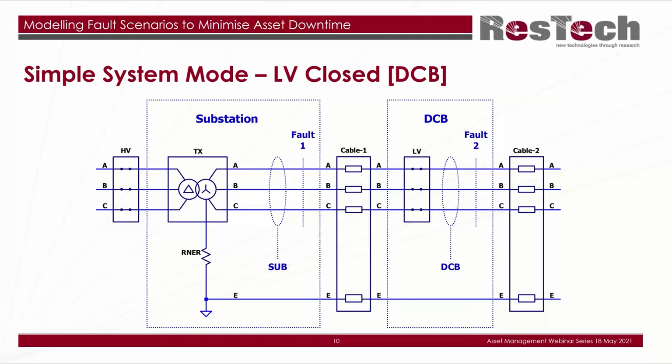Now, of course, if a fault occurs anywhere in a part of the system where power is applied, the fault is revealed. And we'll see the sequence of devices tripping will give us clues as to where the fault might be, and what the currents and voltages are doing will also give us clues as to where the fault might be. Okay. So this simple system has basically 4 modes of operation, and of course, if you have more things downstream, that would create more modes.